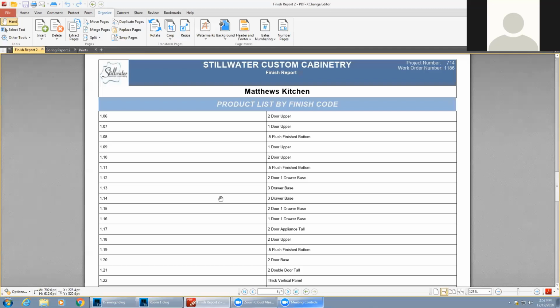The way that Microvellum specifically integrates to that is we take the material file for purchasing, and we initiated our own internal reference number system. So if you have a 10127, we know that 101 is maple and part 27 is a piece of 3/4 by 3.5 inch hardwood by the lineal foot. Every IR number that we have comes from Microvellum. Again, we wrote a report called a BOM report, or bill of materials, and it summarizes all of that.